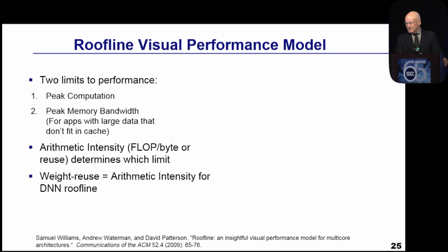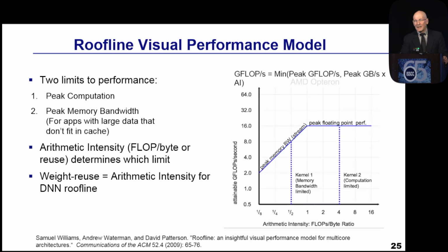What about performance? To explain the performance, it's not just peak performance, it's the actual performance of delivered things. A useful graph to show that is called the roofline model. The roofline of the chip has a flat part and this diagonal part. The flat part of the chip is kind of the speed of light. For the TPU, you can't do faster than 92 teraops per second. It's physically the speed it will go.